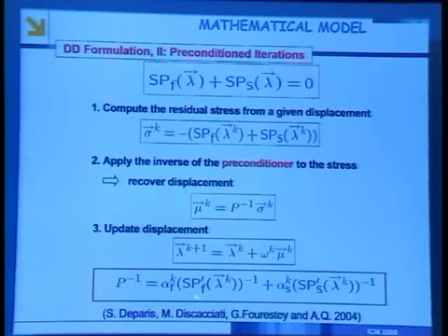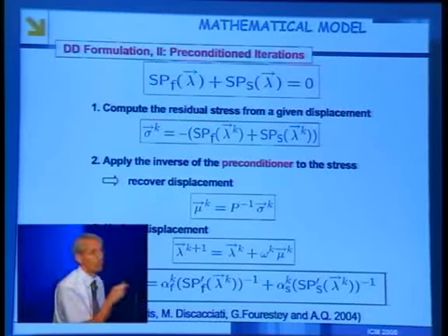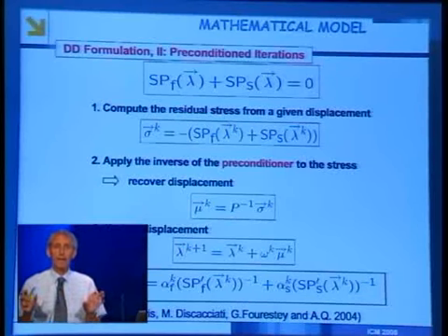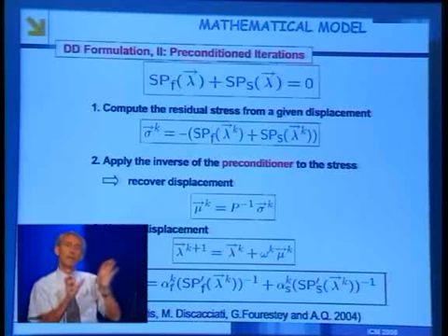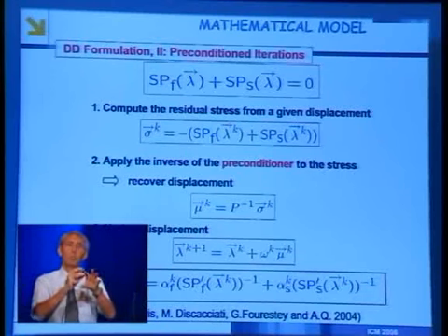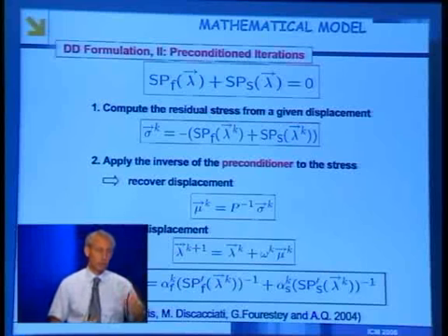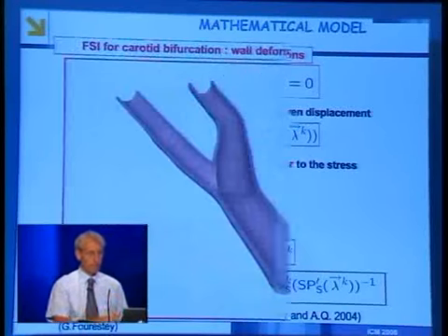We take the linearization of the Steklov-Poincaré for the fluid and the Steklov-Poincaré for the structure, and we take the inverses and we sum up the inverses, and we weight them by suitable weights. And this is the inverse of our operator. So roughly speaking, at every step, we have to solve independently a fluid problem from one side and the structural problem from the other side, and recombine the 2 stresses that we have and proceed according to this conjugate gradient method, say.